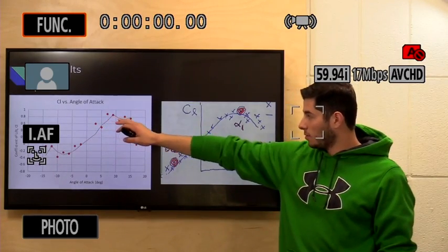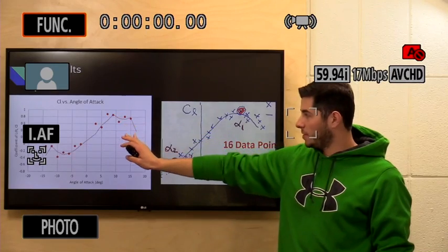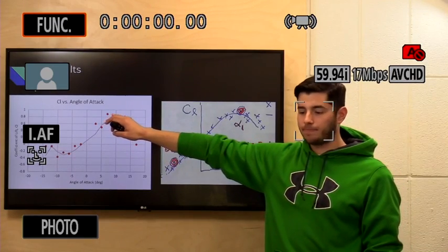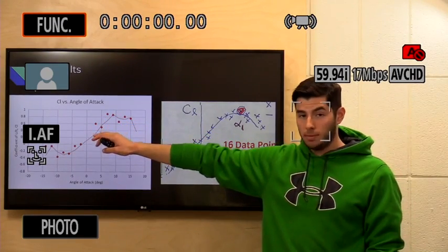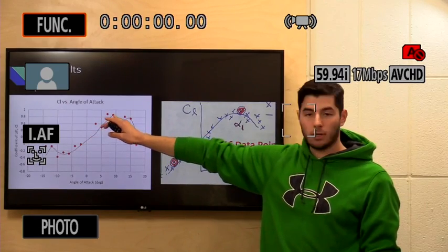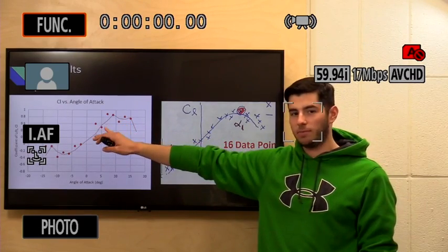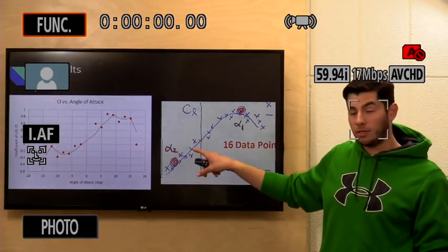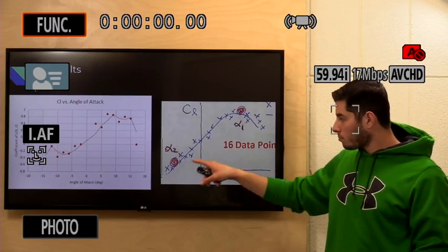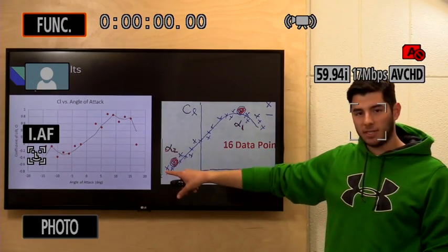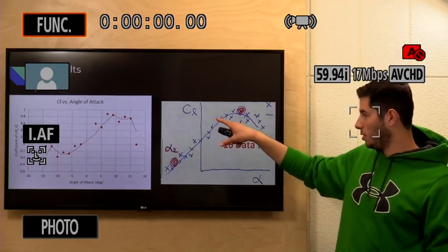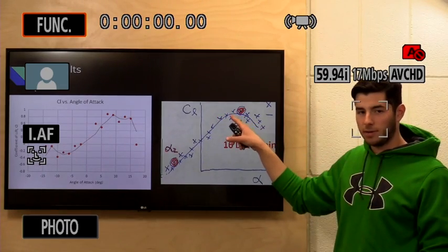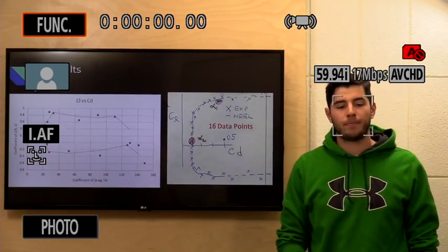However, as the graph dips down, that's where the airfoil is stalling because the boundary layer is separating very close to the leading edge, and therefore it's unable to produce any lift. This is pretty accurate and consistent with what we were expecting to find, as given in the assignment sheet. It increases linearly with angle of attack and then decreases around the stalling point of the airfoil.